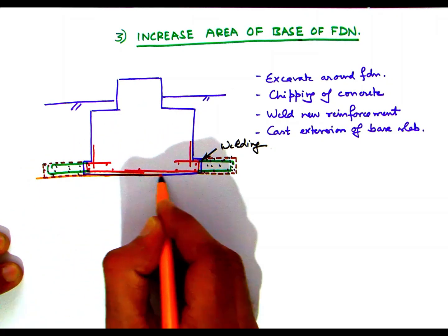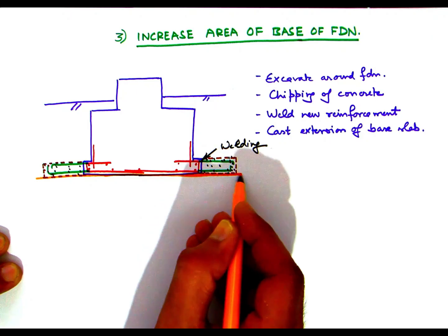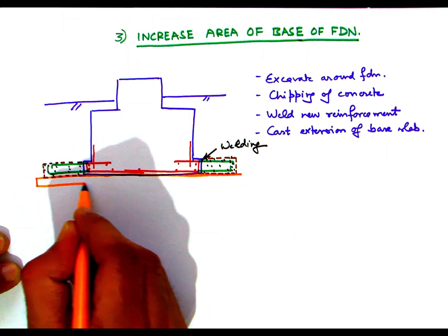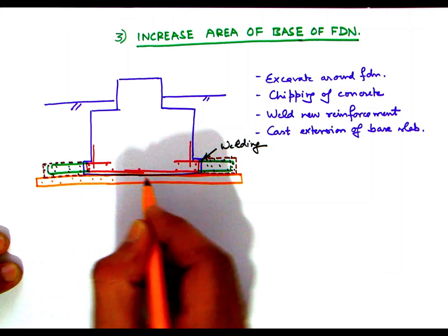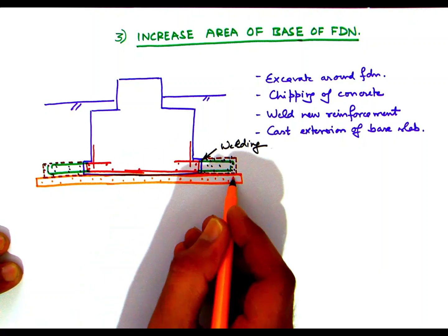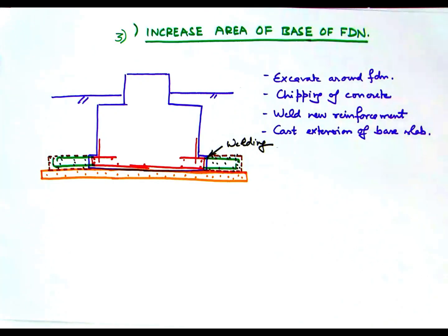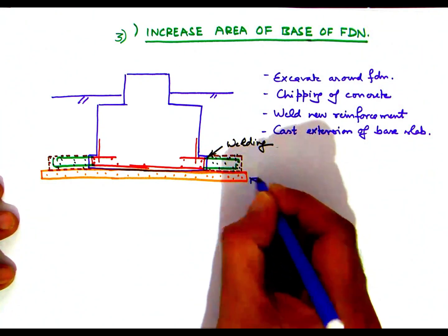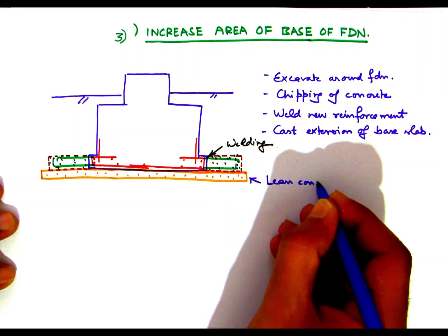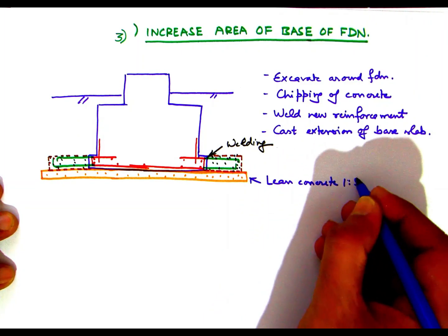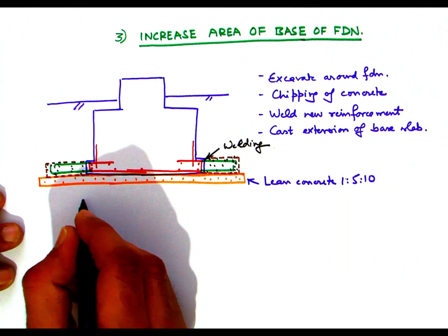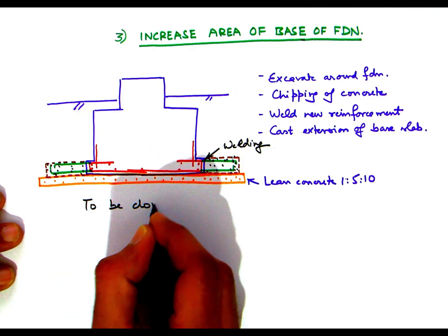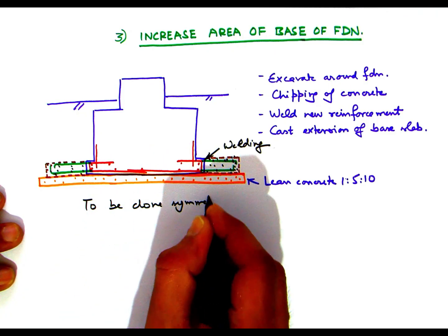It should be noted that the plain concrete layer, which is usually provided below the foundation slab, also needs to be extended. It's important that the process is applied symmetrically around the foundation, and care must also be taken that alignment of the foundation system is not disturbed while the construction is taking place.